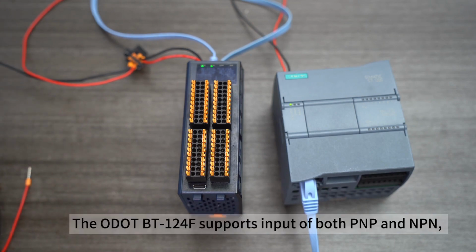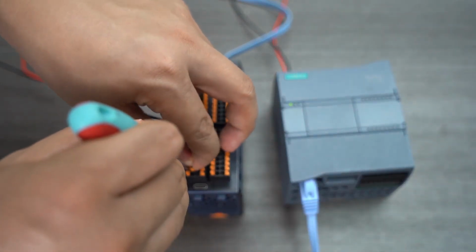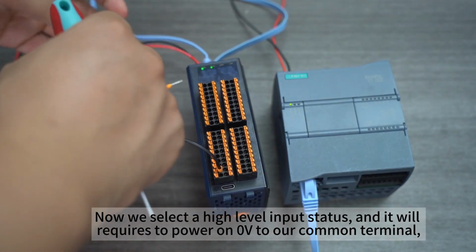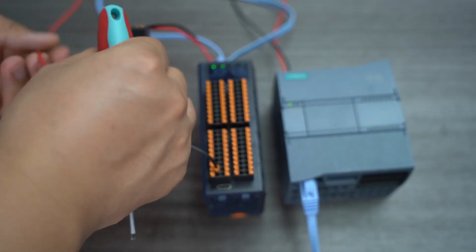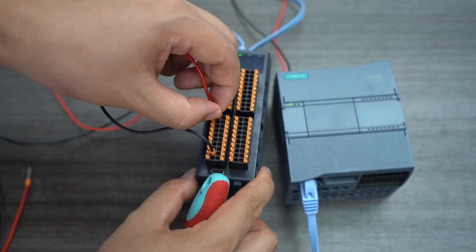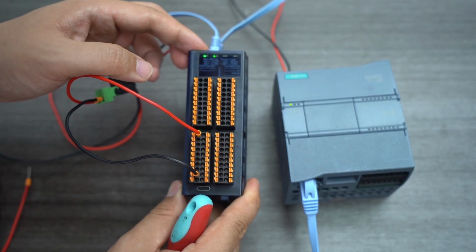The ODOT BT124F supports input of both NPN and PNP. When we choose different common terminals, the input will be different. Now we select a high-level input status, and it will require us to connect 0V to our common terminal. Then we could have one high-level input. Then we use 24V to light our LED, and we can see our channel LEDs are all on.